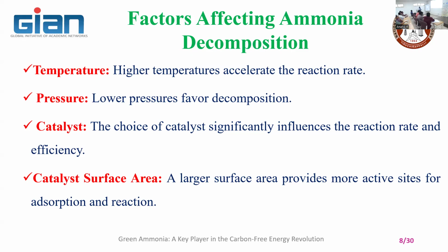if it is possible to ensure that the breaking of ammonia happens at lower temperature, even at 200 degrees centigrade. But if we go for thermal decomposition, the temperature is around 700 to 800 degrees. At 200 degrees itself, we are able to break the ammonia into nitrogen. Then the minimum amount of energy you are going to consume for the reactor for the endothermic process is going to be reduced. And also increase the surface area, right?